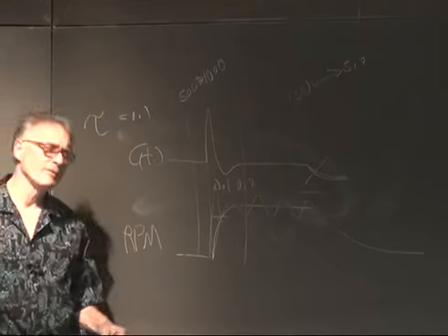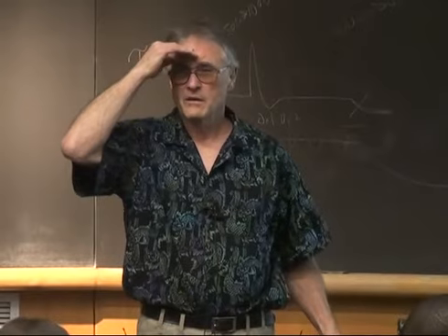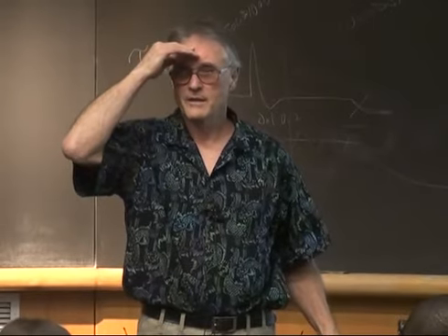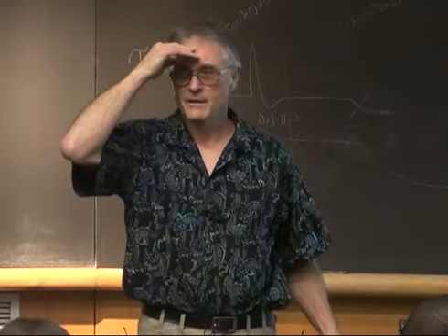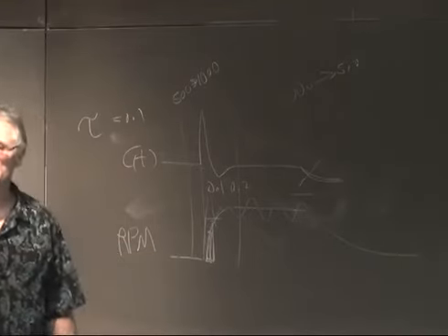If you look at a square wave, the time constant of the circuit corresponds to 0 to what percent? Zero to 63%. 1 minus 1 over e, right? So one time constant would really be down here, so you can't get that time any shorter than 0.1. So this has got to be above 0.1.